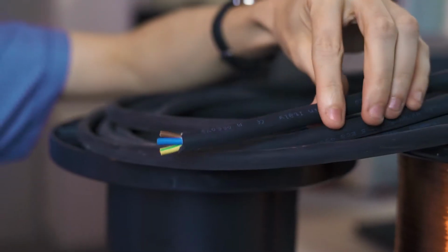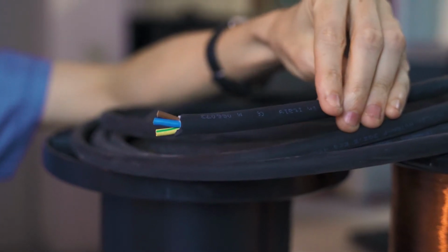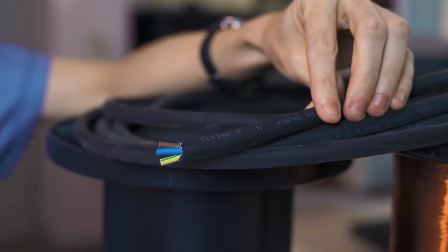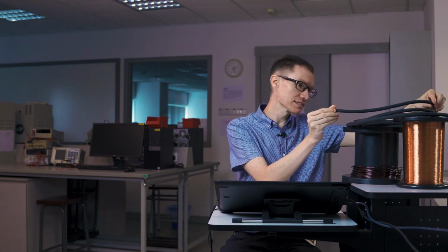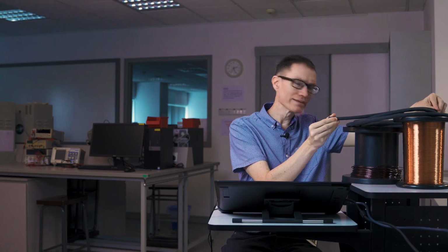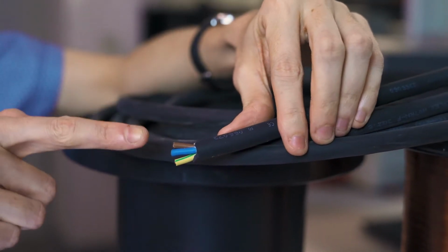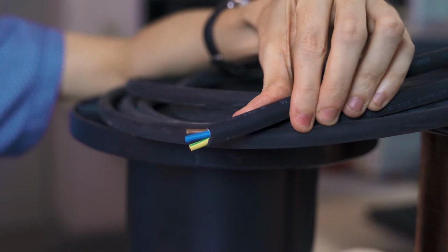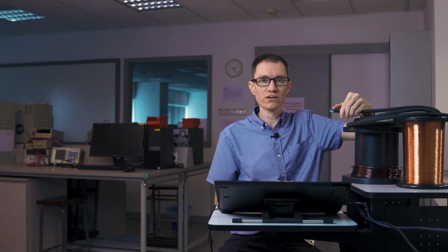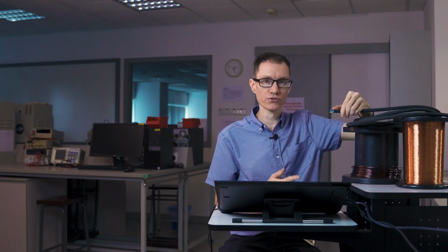I also have a cable up here. I'm calling it a cable rather than a wire because it actually has 3 wires inside. This is 13 amp wiring, and it says on the side 13 amps made in Italy. It follows the European standard for the color code here. We have a brown wire, a blue wire, and a striped green and yellow wire. The brown wire is for hot, the blue wire is for neutral, and the striped green and yellow wire is for ground. If a wire can carry more current, then it's going to have to be thicker than a wire that doesn't carry as much current.